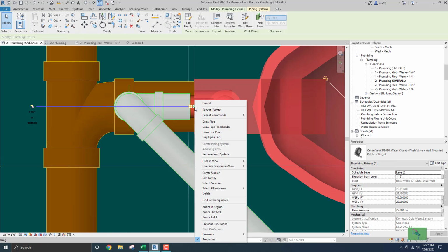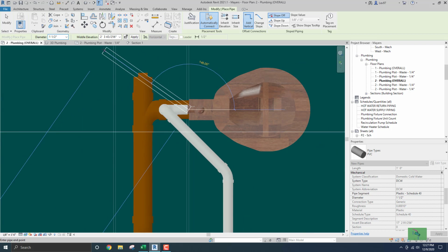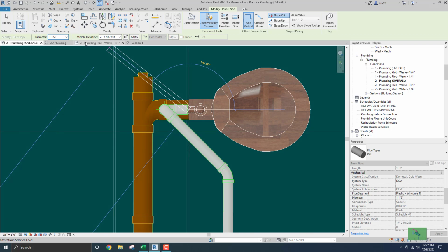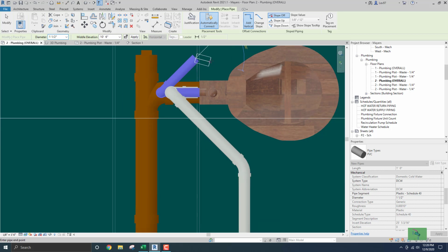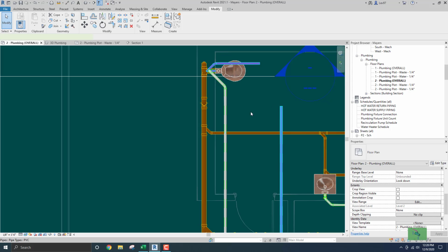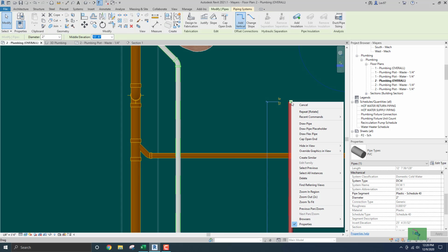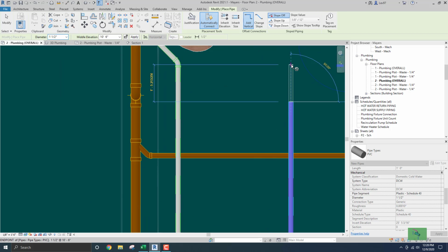Okay, right click, draw pipe, PVC, domestic cold water. Why is the slope off? Middle elevation, that's the default elevation. I'm going to bring it all the way out here. Change this to a 10'6" elevation. Come out 135 and go over just for clarity. Now it's in the ceiling at 135, and here I'm going to put a reducer. I'm going to reduce the 2" to a 1 1/2 inch, because that's the size.